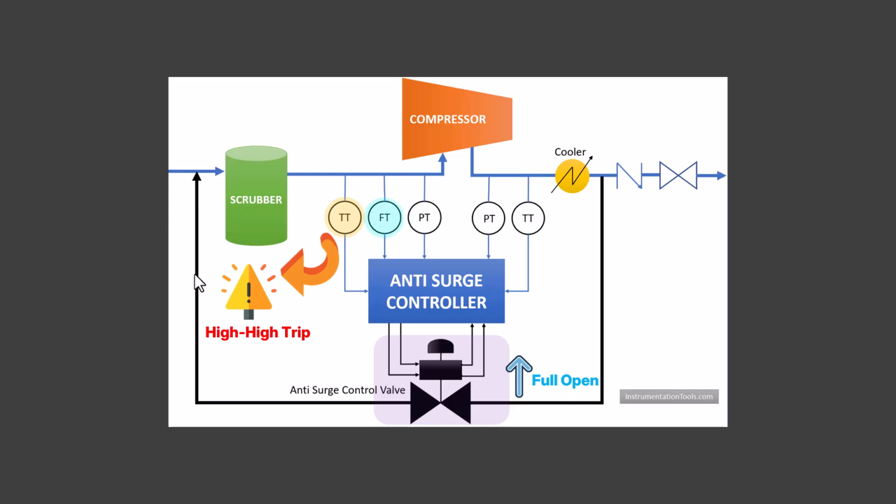A preventive maintenance PM job was scheduled on the compressor suction flow meter. Before starting the work, the operator checked the list of available MOS points. Since the suction flow meter was not included in the MOS list, he assumed that performing maintenance on this instrument could not trip the compressor. The maintenance team started working on the flow meter.